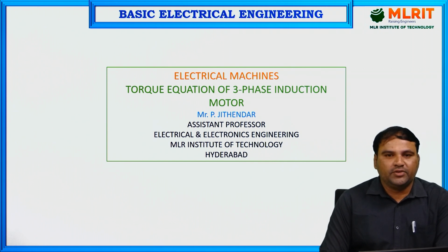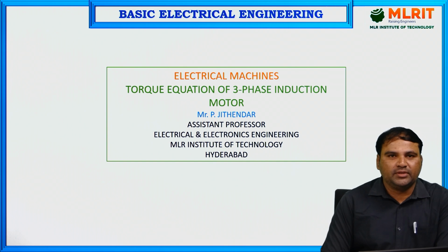In today's video session, I am going to discuss the torque equation of the three-phase induction motor. Previously we discussed the torque equation of the DC motor, that is 0.159 into phi Ia Zp divided by A. In that case, torque is always directly proportional to phi into Ia.